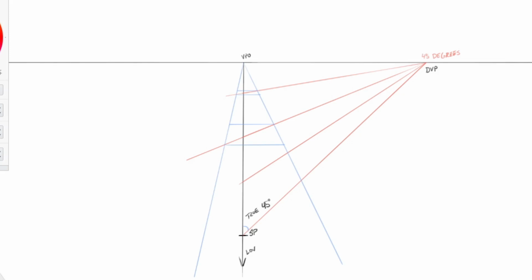Today I'm going to answer a question that some people have a little bit of confusion with. How do we create a cube in one-point perspective? As you may know, in one-point perspective we don't have measuring points like we do in two-point perspective. So what you're seeing in front of you on the screen here is how we accurately calculate a cube according to the single vanishing point that you have and a directional vanishing point.